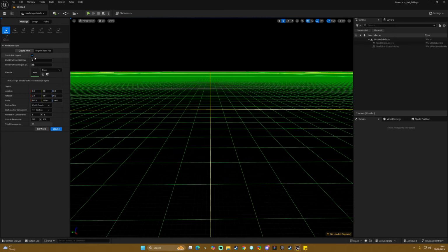But if you are dealing with massive terrains, I would suggest flicking this off, just because once you start adding things like a landscape material, the memory usage of your graphics card's VRAM is going to start going up rapidly, and this only adds to that stack of resource usage. So in this example I'm actually going to turn it off.